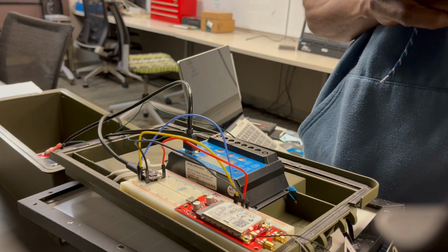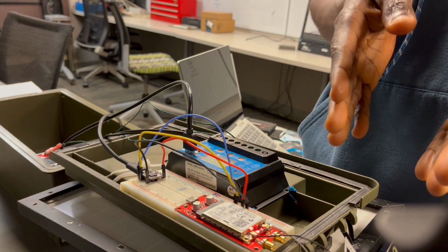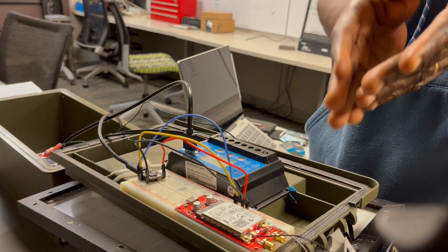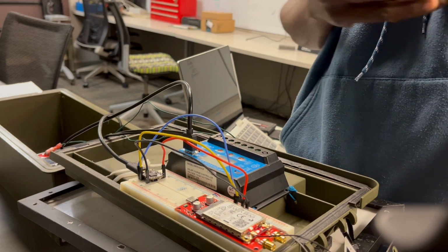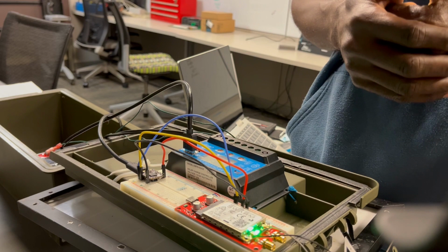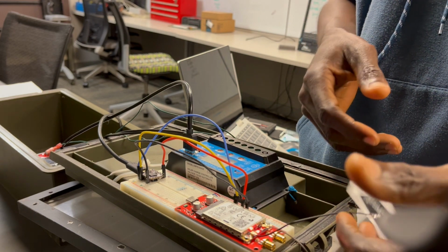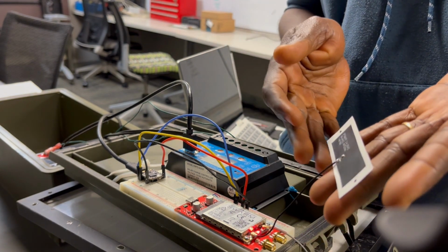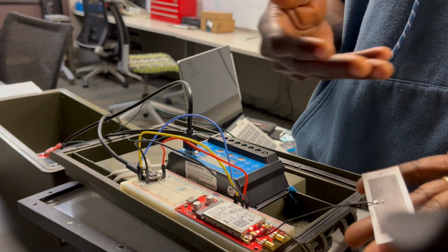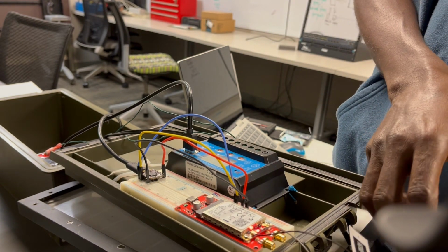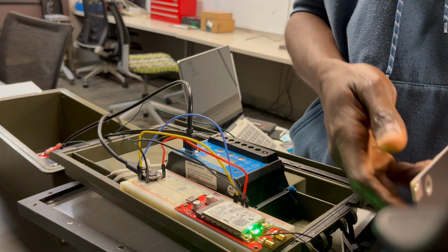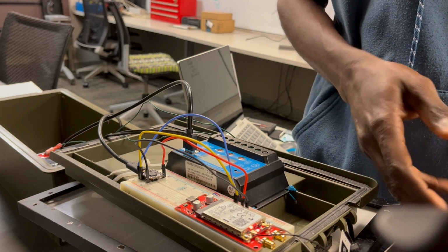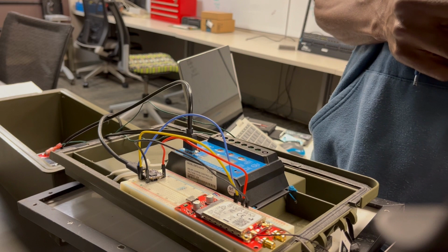In addition, the receive pin on the Swarm board is connected to the transmit pin on the QT-PY, while the transmit pin of the Swarm board connects to the receive pin on the QT-PY. And of course, I also connected grounding. The Swarm board comes with a GPS login system that is able to hook onto the GPS so that the satellite can communicate. It comes with the UHF antenna, and also has that connection over there for communication with the satellite. So we are fully set up.